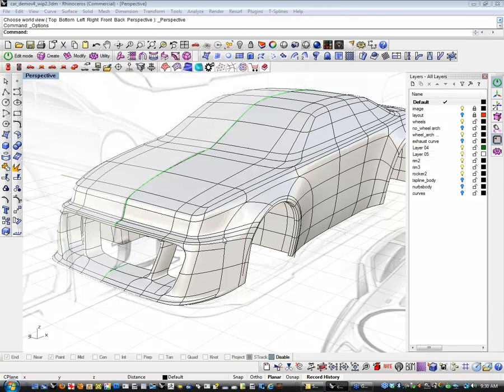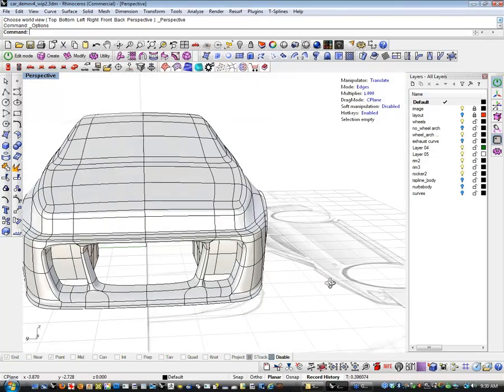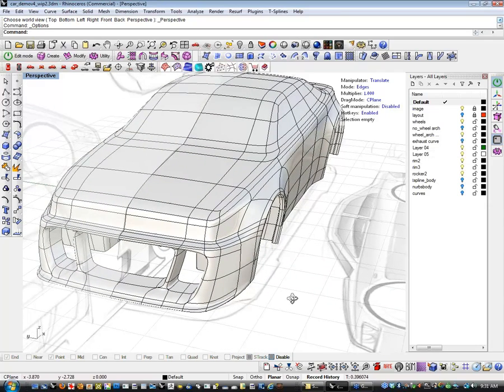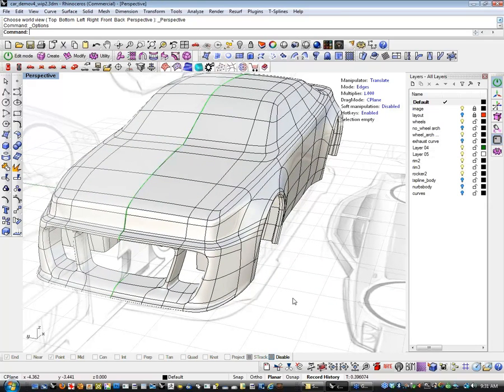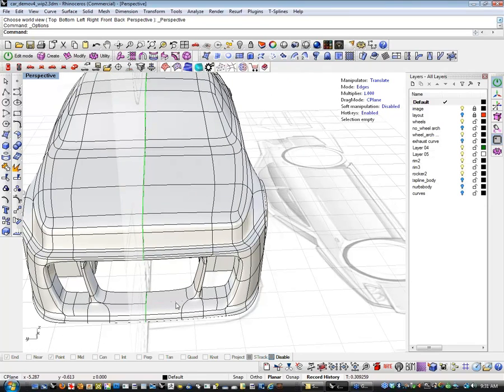There's a question coming in about how, if you use old NURBS knowledge from Hans, it says that you should try to get isoparms joining nicely with no tangency jump. This is not done here in the bumper. Is it a good idea to keep nice isoparms? I wonder if he's referring to those star point regions.